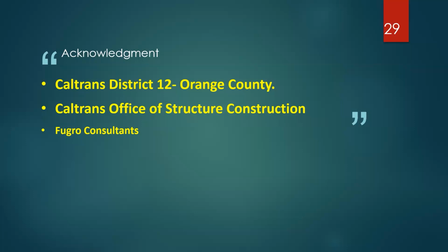Not only that, it reduced the risk of change orders or perhaps even RFIs and claims, because if you could argue that, well, no, we think there is liquefiable soil, and the contract says, no, I don't think so, my borings don't show any of that. CPT went a long way to bring better communication with the design-build team and a smoother and more efficient delivery, which happened in this case. So it was an excellent tool. I don't know if that answered your question or not, but yeah, it does.